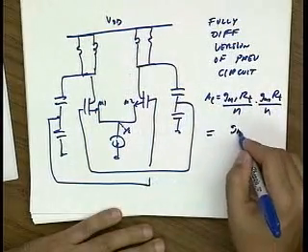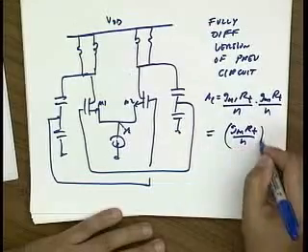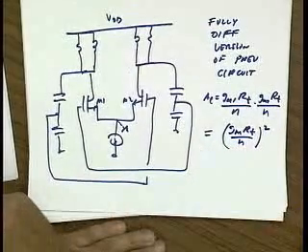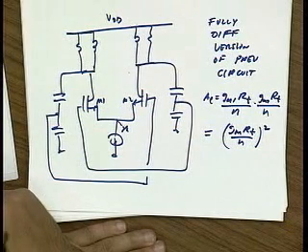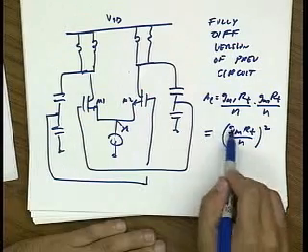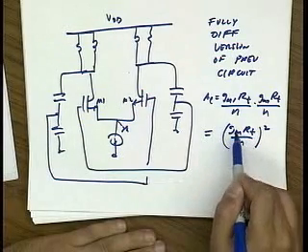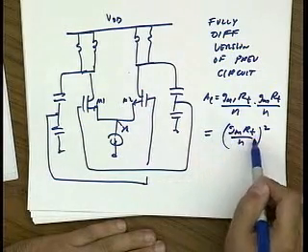In other words, the loop gain is GM RT over N squared. So that's the benefit to using a differential circuit. You might argue that for the same current, this GM is actually reduced, right? So it's GM over 2.